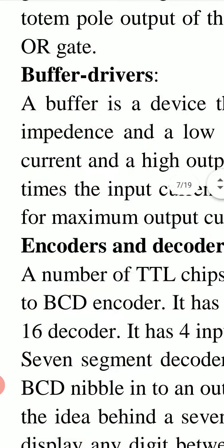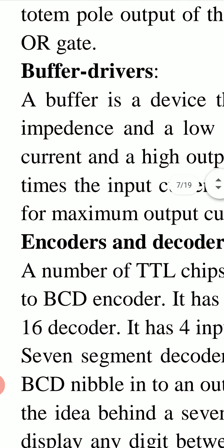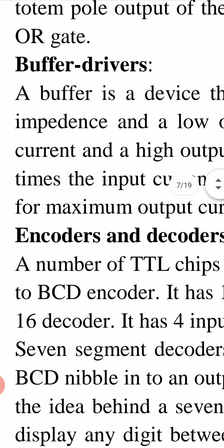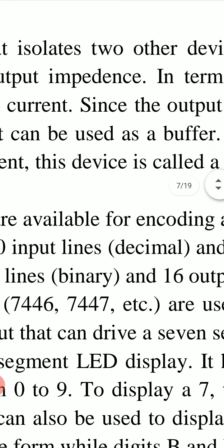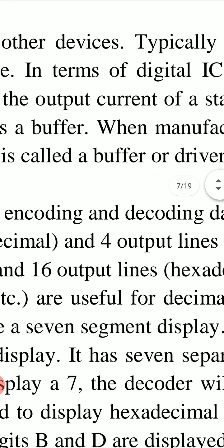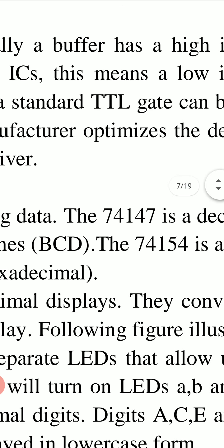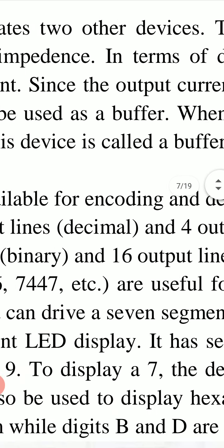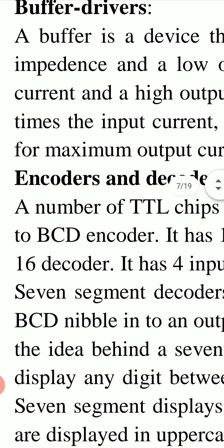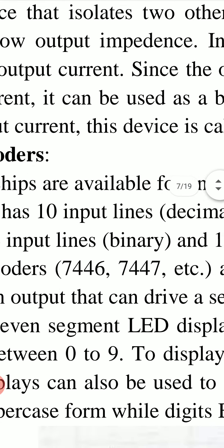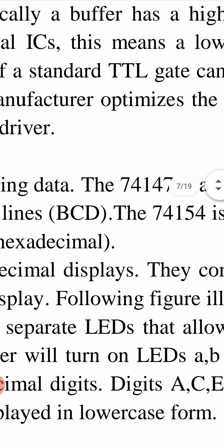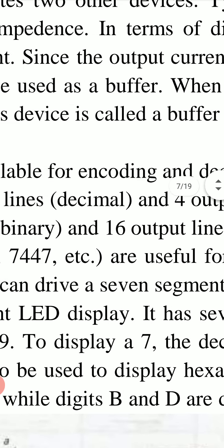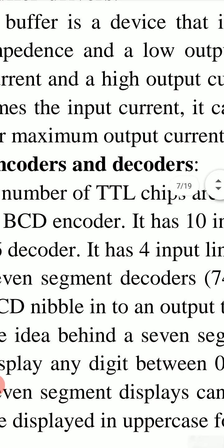Buffer drivers. A buffer is a device that isolates two other devices. Typically, a buffer has a high input impedance and a low output impedance. In terms of digital ICs, this means a low input current and a high output current.